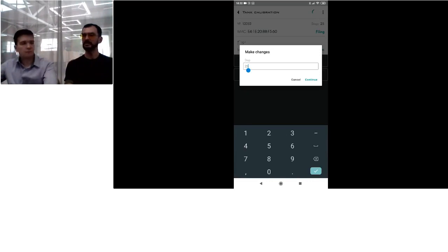Let me just add something here. If you have the sensor with a collet connector, you might as well do that for that particular point, where the collet connector connects two parts of the sensor. As far as I know, that is also a change in the geometry, however not of the tank but of the sensor. We have discussed it with a few guys who have done installations of the long sensors, and they do recommend doing that for that kind of extending sensors. That's a very valuable observation and recommendation.